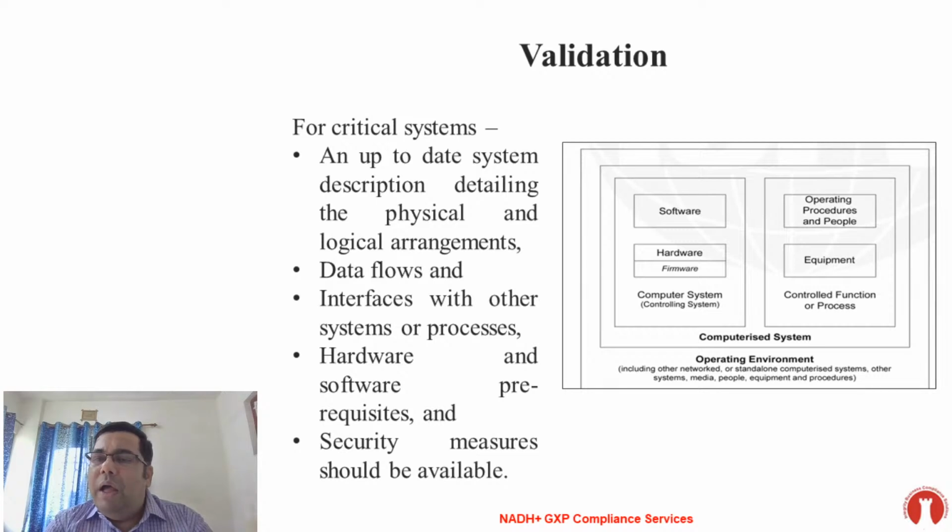Mr. Anurag has asked, how can I approach validation of computer systems in product equipment and requirements? I just want to tell you that computer system validation and equipment validation are basically the same process flow. URS, DQ, IQ, OQ, PQ, everything will be the same. In production equipment we perform the challenge test, and here also we perform the challenge test.